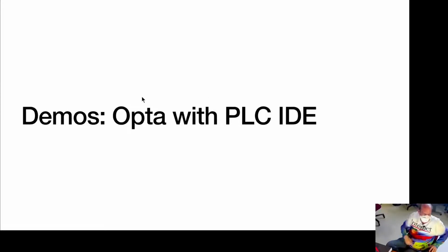We got a question from the interwebs. Can you PWM things with relays, or is that inadvisable? You absolutely cannot. You can turn relays on and off, but the frequency that PWM would turn an output on and off would destroy a relay. It would arc the contacts.